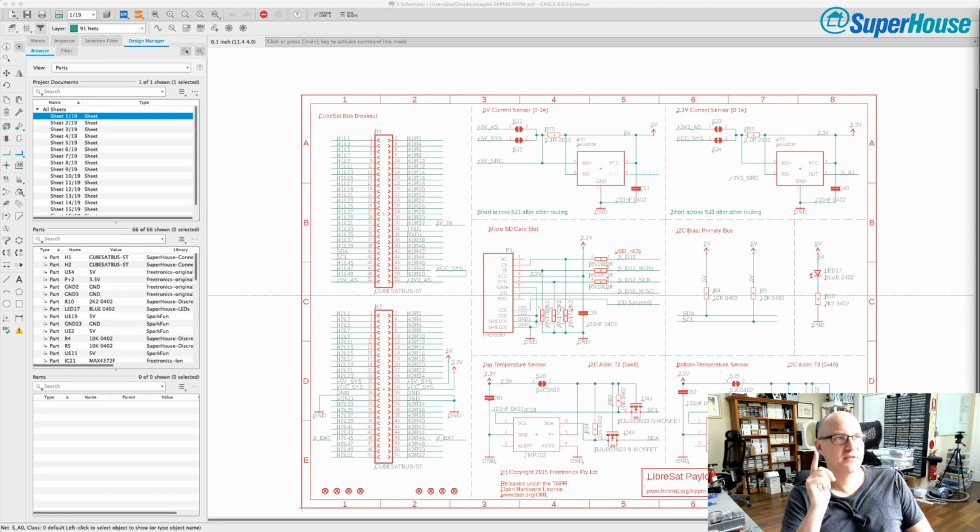Oh yeah, that would work even if the Sonoff failed, because what would happen is the Sonoff would fail and the relay would end up in its normally closed position, and then the light switch would continue to work as normal. So yeah, you could do that.